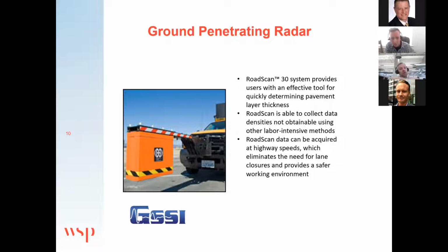Because what happens, you've got the signal going through the air and then into the ground, so you get losses. Coupled is better, but you know what? When you're moving at speed, there are advantages to air launch. You haven't got this rig that's hanging just above the road, bouncing on things. These air launches have their own advantages. So the combination of air launch and ground coupled is good. Okay, so let's have a look now.